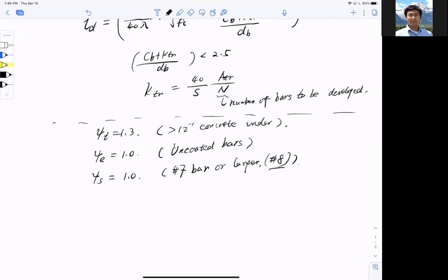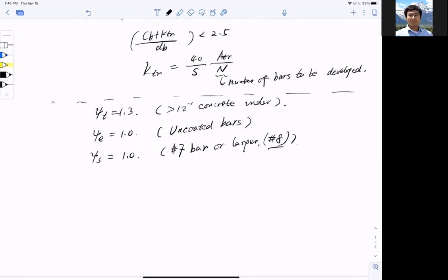So now these are the coefficients. Not too bad. Now I'm looking at the confining factor, so I start looking at cb, the concrete cover. Remember what cb is? cb is the minimum of c1, c2, and so on. But I want to do drawings and visualize it, so everything's graphic. Essentially, this is my bars at the corner. In this case, my section looks upside down. So that is my corner. I have cx, which is from the edge of the concrete to the center of the bars, and cy, edge to the center.